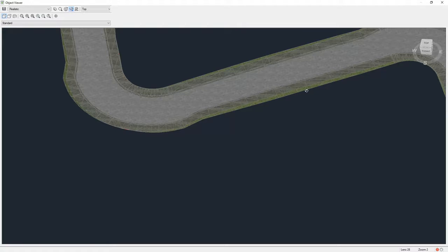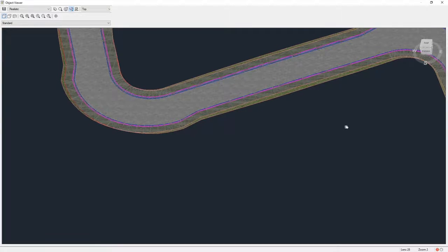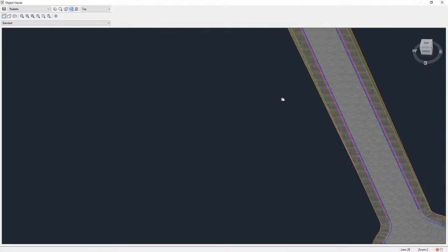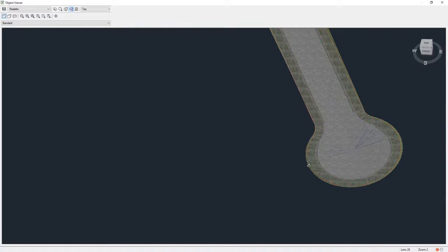You can see some grading going to the daylight of the existing surface. And then when we move into the cul-de-sac, instead of having that jagged angular cul-de-sac, because we changed to 5-foot increments, we now have this well-defined circular cul-de-sac that is correctly targeting the centerline profile of our dev alignment going along the curb line as we hoped it would.